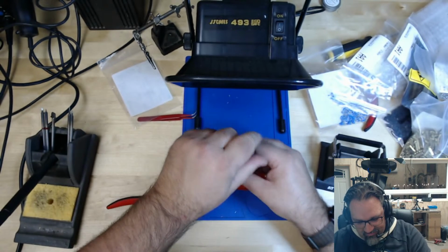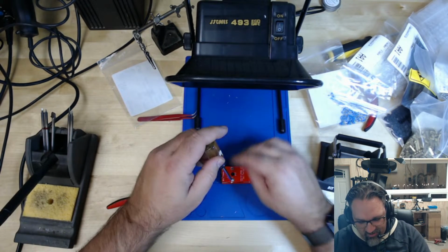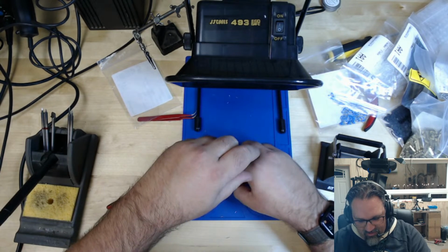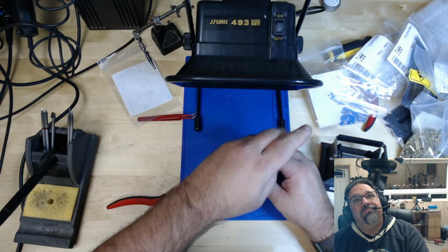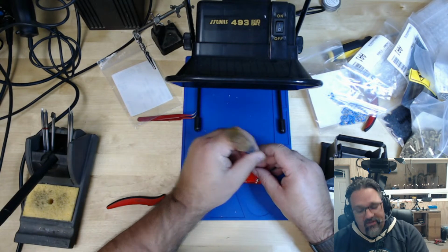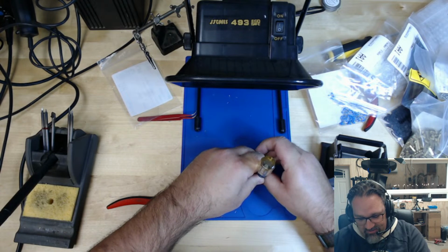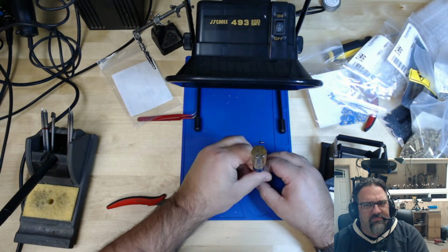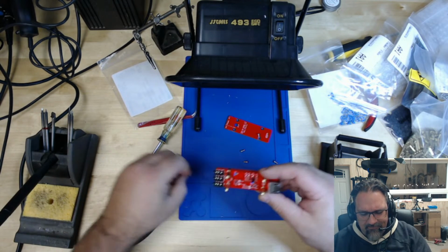Solder the jumpers onto the board so that you can jumper it with or without the mic preamp, and for CTIA style, the 4-pin or separate mic and headphones, and also the microphone type, whether it's dynamic or electret. Whether you put the mic preamp in circuit or not.